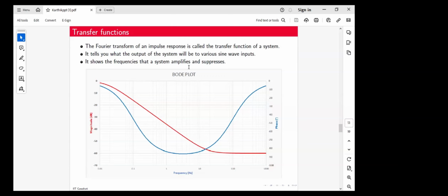I don't think that depends upon the frequency per se. The moment you have phase distortion, you will always have the signal spread over a larger time amount. So that would just replicate the frequency response of the human ear. The frequencies that the human ear hears well are the frequencies at which you will also hear the distortion. The frequencies that you don't hear well, you won't hear the distortion either.